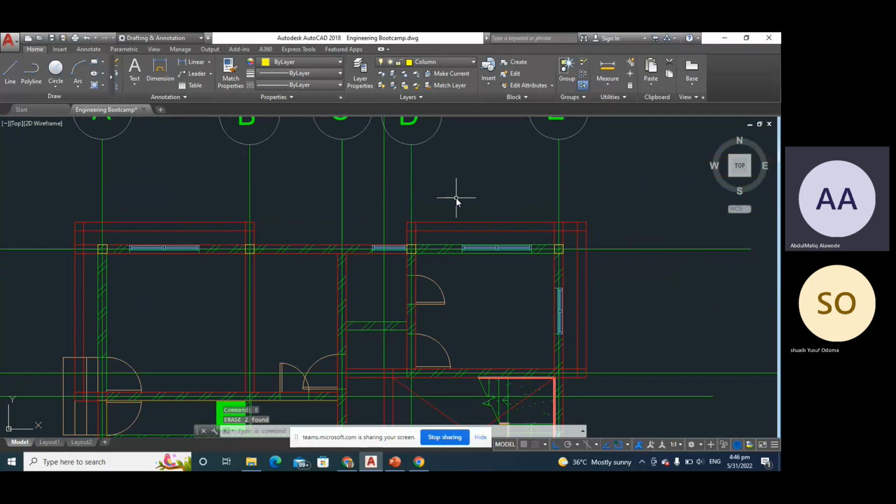Remember I told you last week that if you are using a 230 by 450 beam, you work with the deflection condition as stated in the code. If you are working with a continuous system and a rectangular section, although this is not a rectangular section, when you are doing your sizing it's always advisable to use the rectangular section as your baseline of sizing.